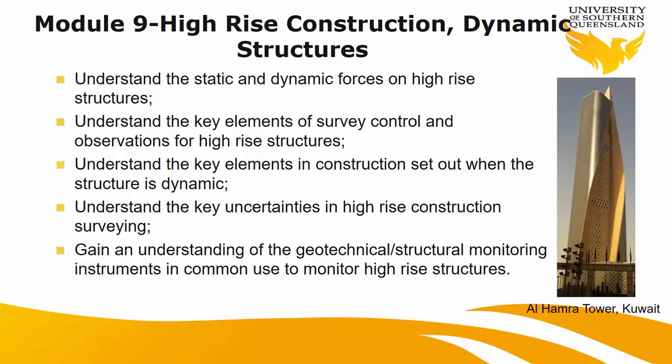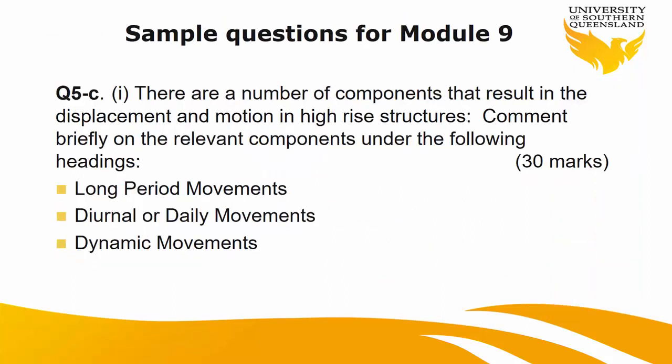We actually take it a little bit further with the high-rise module. I will try to say how you actually monitor, what the different monitoring systems are that we need to have for different types of buildings, whether it's multi-story, mid-rise, high-rise, or super high-rise, the techniques are different. We talked about the different types of movement: dynamic movement, static movement, diurnal movement, which is happening daily, the different types of movement that your high-rise can have, and how you're going to monitor those. Are we good? So that was the main thing we've learned.